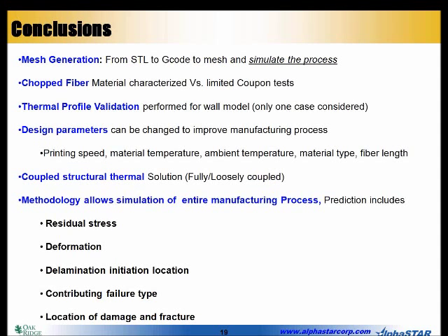To conclude this presentation, we have created a mesh generator which can read either an STL file or a G-code to generate a mesh including material orientations and fracture behavior between all the layers, and also the thermal mapping from the initial thermal analysis.